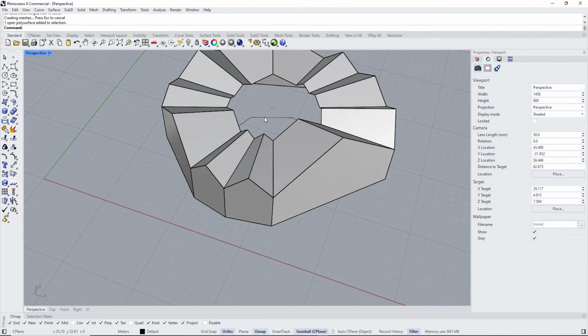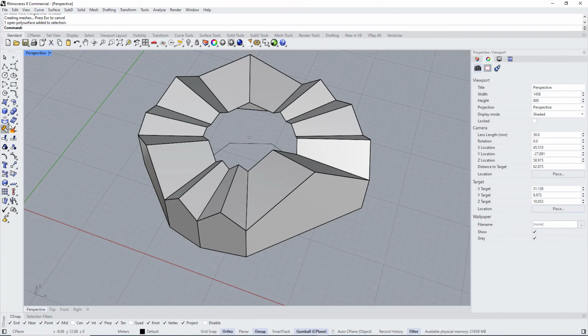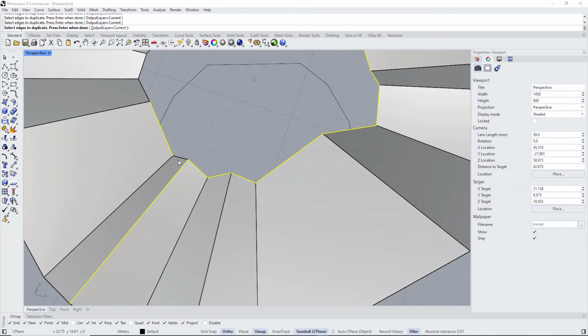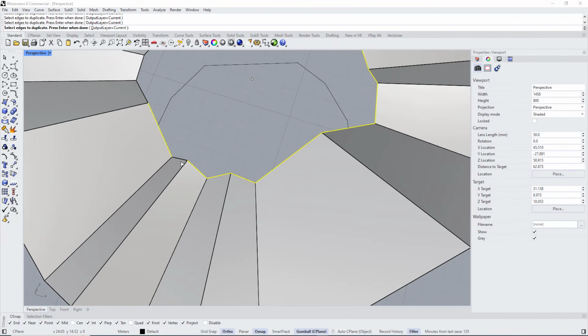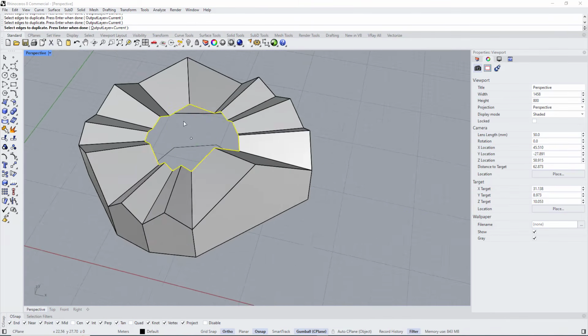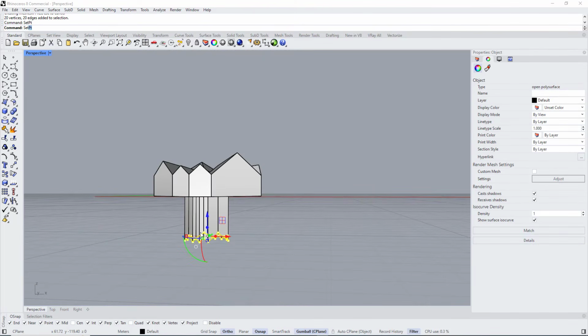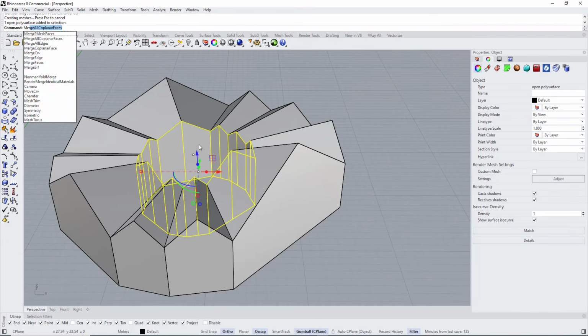We are going to do the same things for the faces inside, but I need to extract the curve, so I'm going to extract to duplicate the edges, to extract the edges from this part. Hold Control to deselect an edge. Right click, Control J to join and extrude, then Control Shift and select edges, set point to Z, and snap it here. Select object and merge coplanar faces.